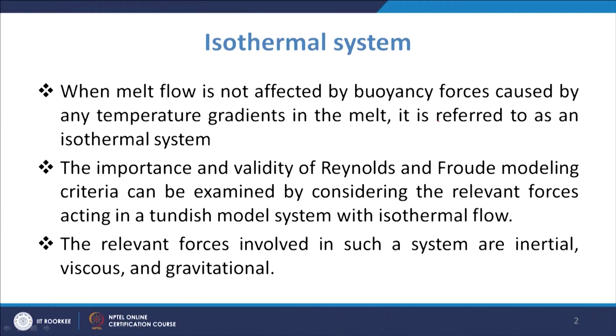And in these cases the importance and validity of Reynolds and Froude modeling criteria can be examined by considering the relevant forces acting in a tundish model system with isothermal flow. So, basically you will have to examine these Reynolds as well as the Froude modeling criteria.